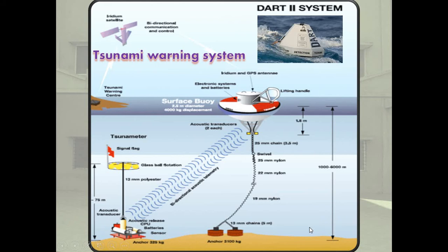The detection of tsunami generation through a network of 10 to 12 bottom pressure recorders that could detect and measure a change in water level of 1 centimeter at water depths of up to 6 kilometers around these two tsunamigenic zones. Monitoring the progress of tsunami and storm surges through a network of 50 real-time tide gauges. Tsunami modeling addressing the inundation and amplification all along the coast and islands for different tsunamis originating from different sources.